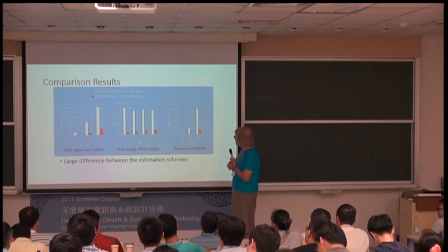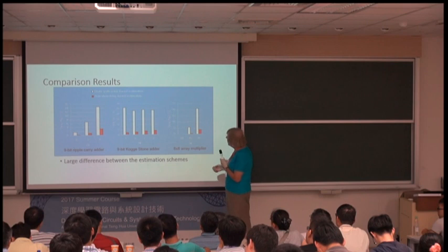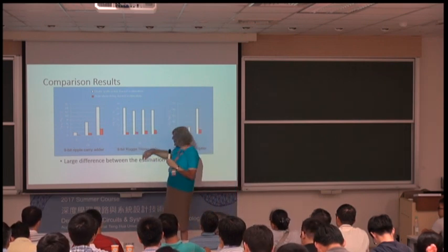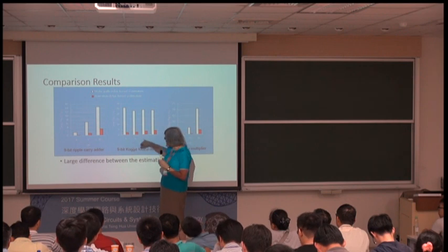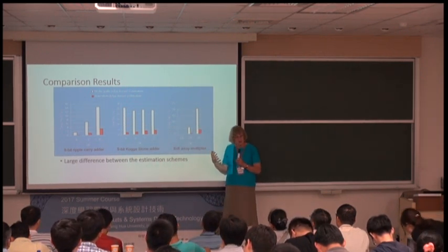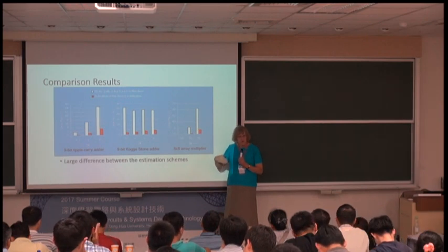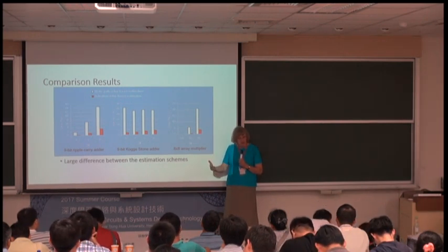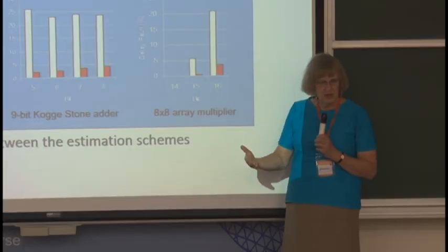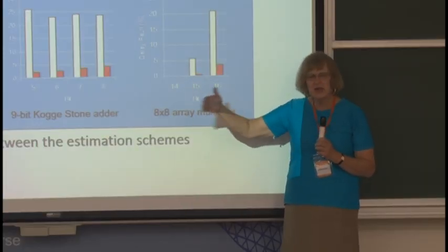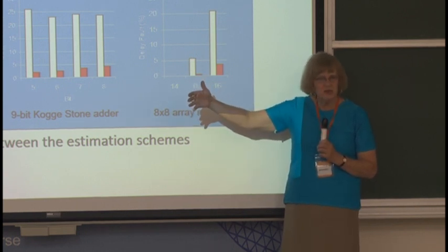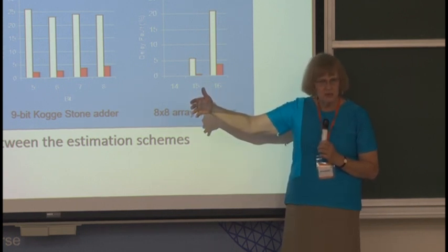Well, this plot shows the number of faults for different bit widths for these different algorithms, right? He generated these plots by randomly generating values, running SPICE, and getting the delay and asking, is the delay bigger than some value we're using for the clock cycle?